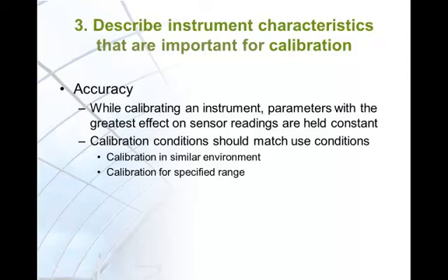Application-specific calibration makes sense, especially when the sensor is nonlinear. A general calibration of the full range is laborious and requires many data points and a statistical regression. For a narrow range, however, the sensor response can be approximated with a linear function that can be determined with tighter precision. Thermistor output, for example, is nonlinear. A calibration that is application-specific with an especially narrow temperature range could improve its measurement accuracy.